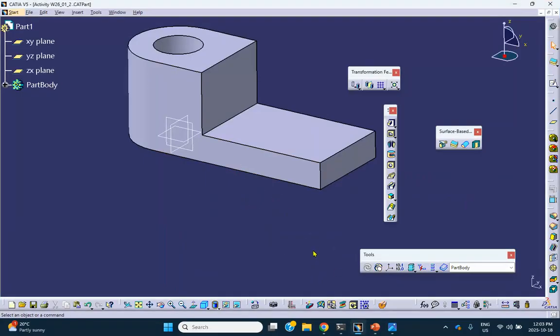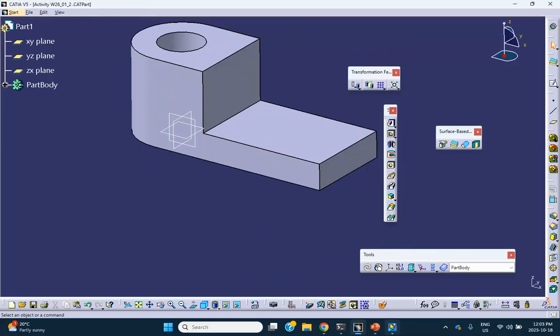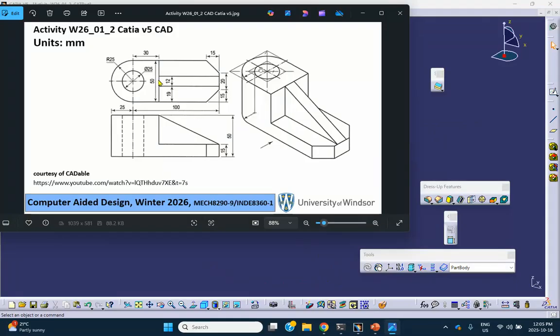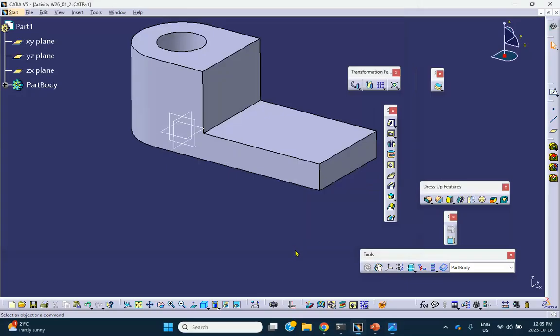So the different ways of doing it, I need a stiffener here, right? What I'm going to do is notice that this plane right there is 19 millimeters away from that plane. So one way to do it is to create a plane which is 19 millimeters away, and then on it draw that little triangle. That's how I'm going to do that. There are other ways of doing it, such as actually creating a stiffener, but I'm not going to do that.